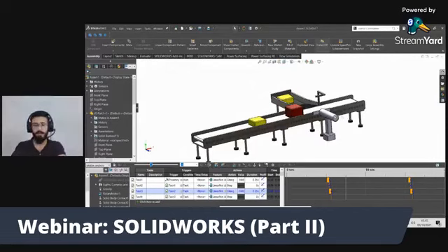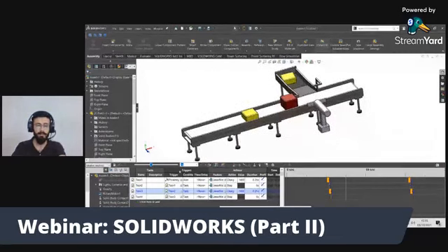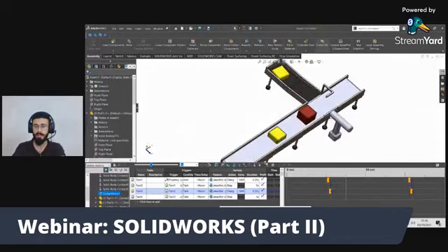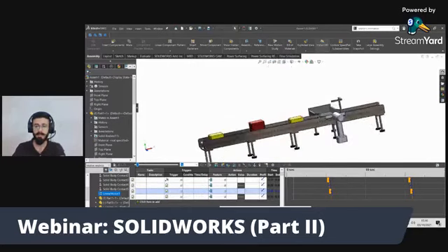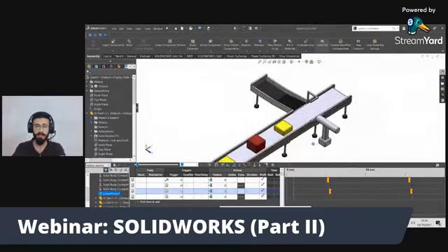This is the use of mechatronic system in SolidWorks. And what are the things I have used in it? Again, solid body contact, so these things should not mix up with each other. Rotary motion of my conveyor belt, and there is one linear motion for my actuator. And I showed this design just to show you what a linear motion is.